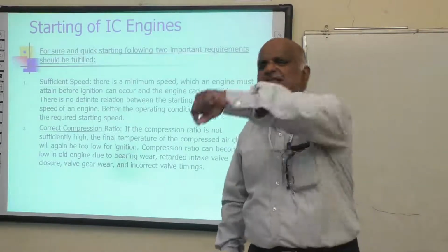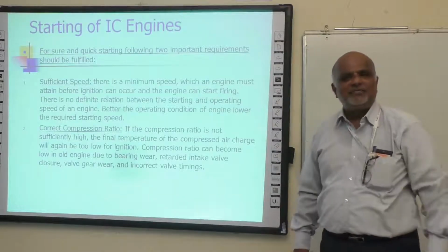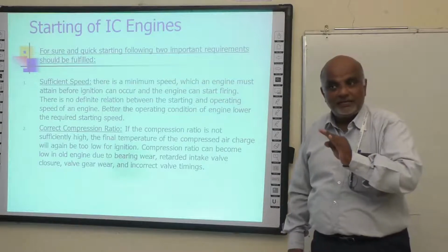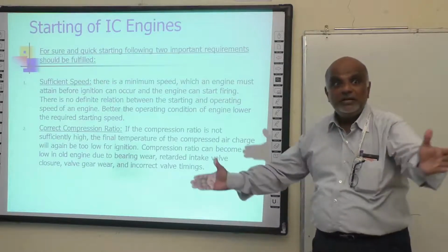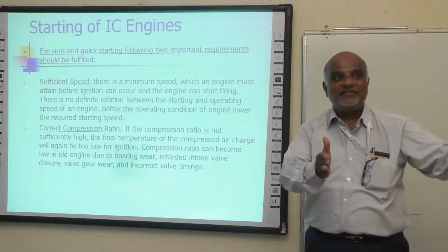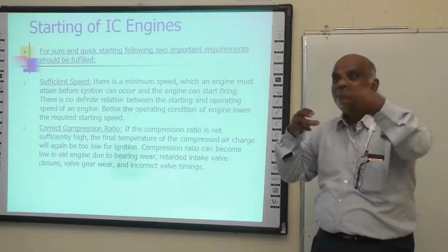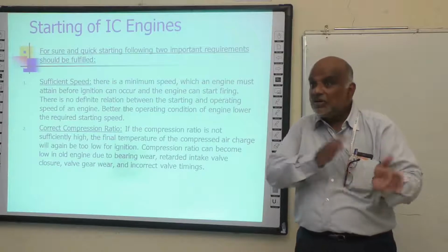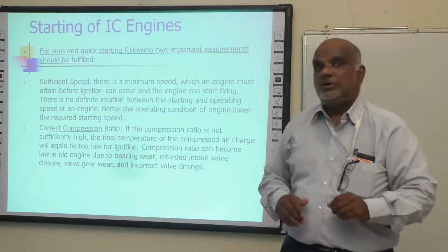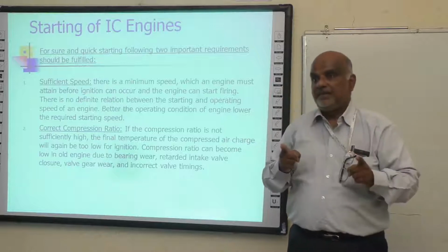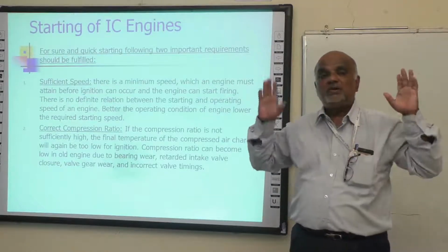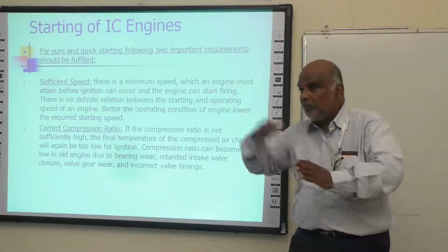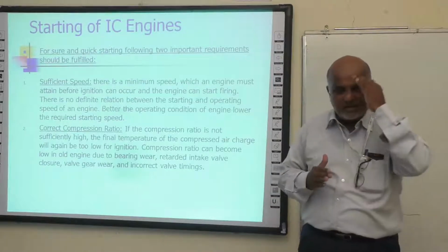Okay. Shall we adopt the same system in our marine engines for starting? We can, but there is a drawback. We need a bigger, larger size battery to energize the self motor and engage it onto the flywheel, which they found was not comfortable. The cost is involved. Anything you do on board a ship, you have to keep this in mind. You are not ordinary engineers just working blindly on what is given to you. It goes on economics. What you invest and what you get out is economics. Keep that in mind.